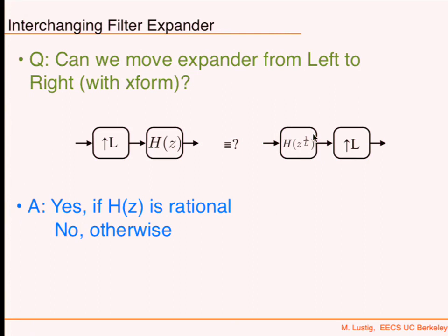So what we're going to do then is what's called a polyphase decomposition, where we're going to break our filter into several smaller filters that can be exchanged. And then we're going to perform that operation using those filters and then combine the result afterwards. Hence, not computing stuff that we're going to be throwing away. So that's the idea next time.